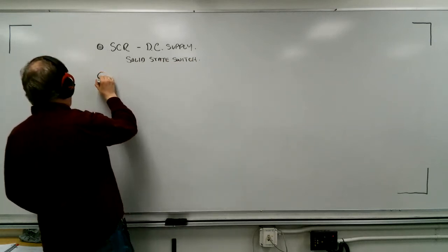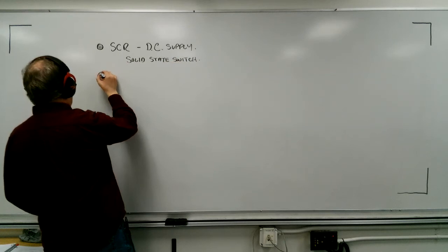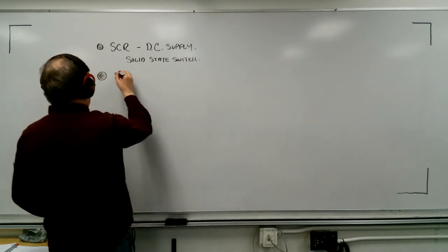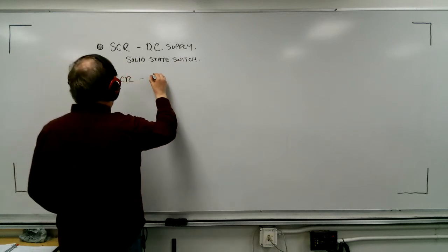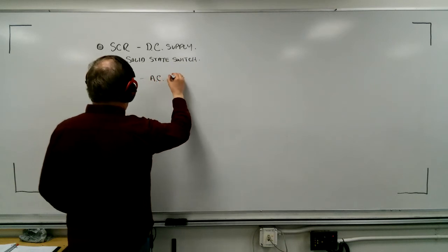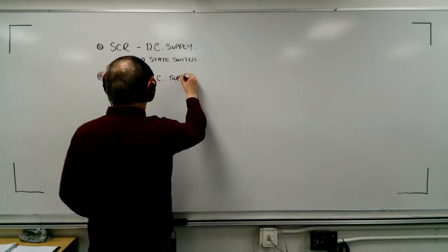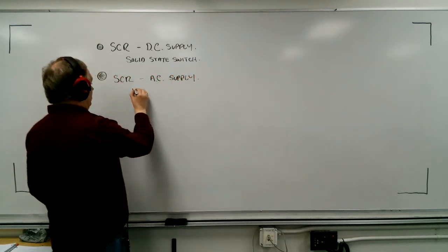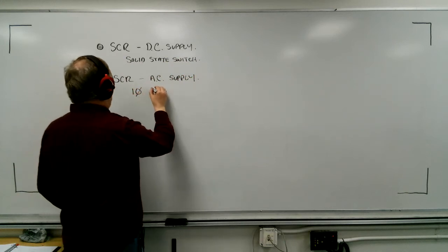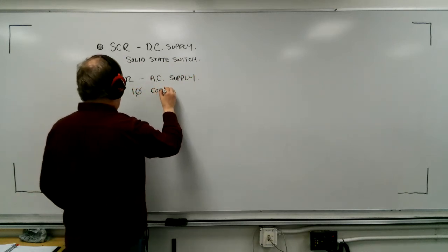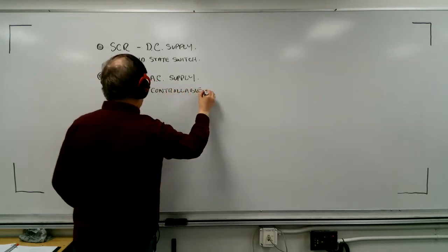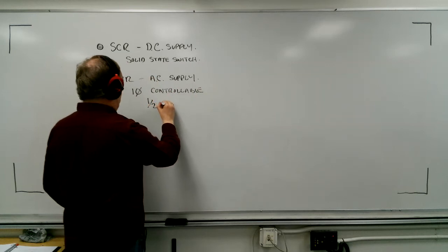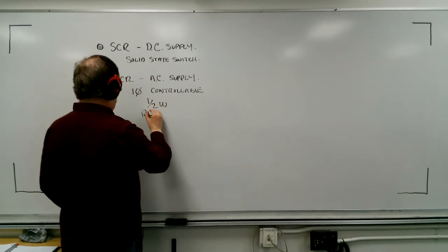The next application, something identifiable as a section, is the SCR used in an AC circuit, AC supply, and we created a single phase controllable half wave rectifier.